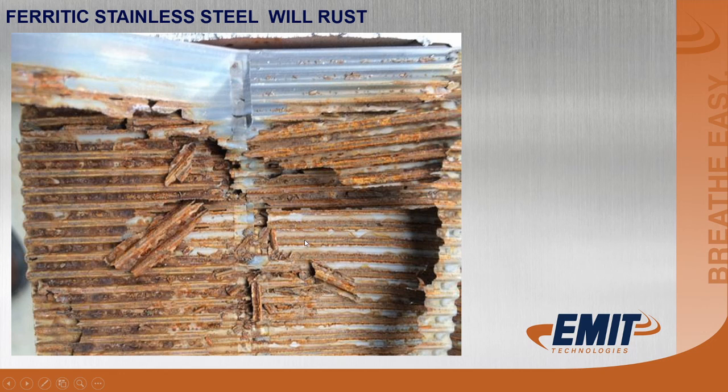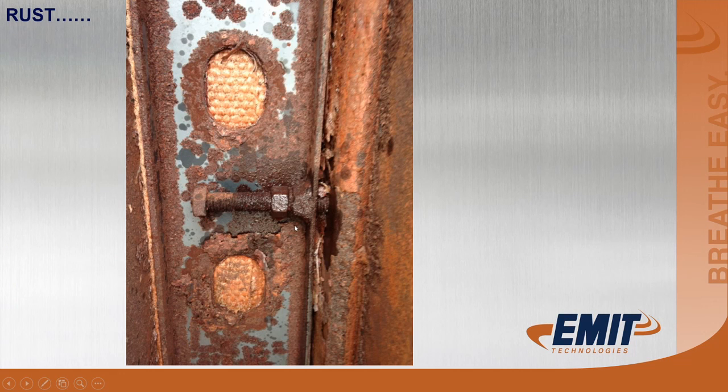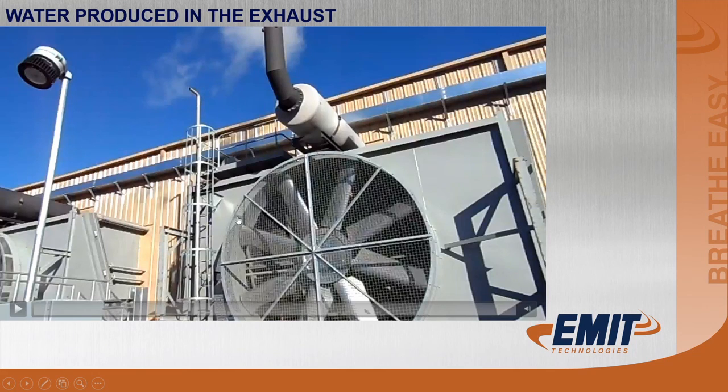This catalyst element was not very old at all. This was in a 3600 series Caterpillar, and this unit was less than a year old. So this is the effects of H2S. Okay. Just to show the amount of water that's produced in a catalyst when you start it, we'll take a look at this video.